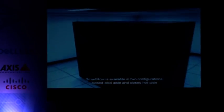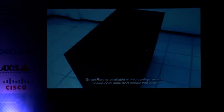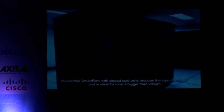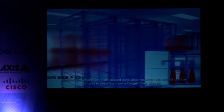SmartRow is available in 2 configurations, closed cold aisle and closed hot aisle. SmartRow with closed hot aisle enhances the AC compressor efficiency and can be placed anywhere, even in environments where people are working. It is the most ideal solution for limited room space. Meanwhile, SmartRow with closed cold aisle reduces the loss of cold air and is ideal for rooms bigger than 20 square meters.